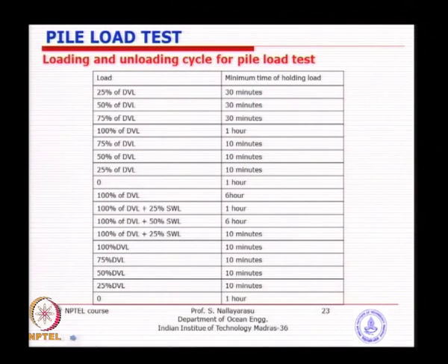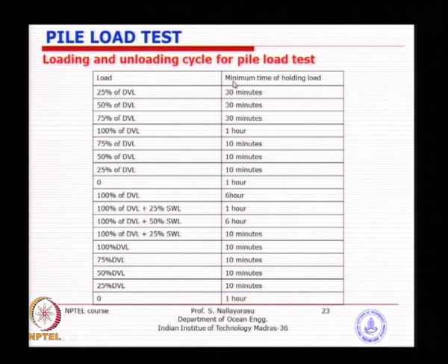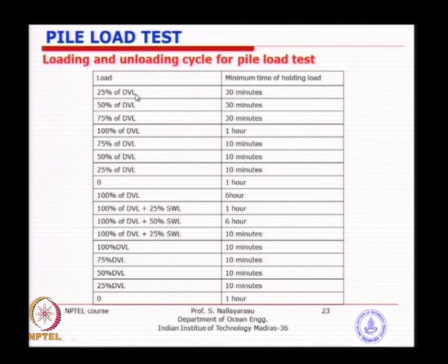In fact, this particular procedure is taken from the pile testing manual, which I was talking about on day 1. So, the design verification load is basically the test load. If it is an ultimate test, the design verification load will be your total load multiplied by the factor of safety, or 25%, 50%, 75%. So, this procedure is just segmented into 4 subdivisions, 30 minutes. Once you load 25% load, wait for 30 minutes, 30 minutes, 30 minutes, and at the 100% load wait